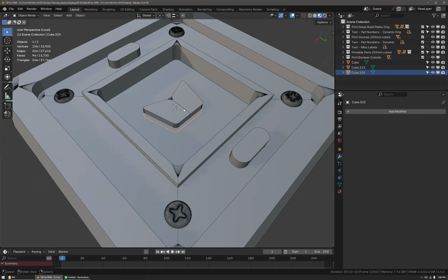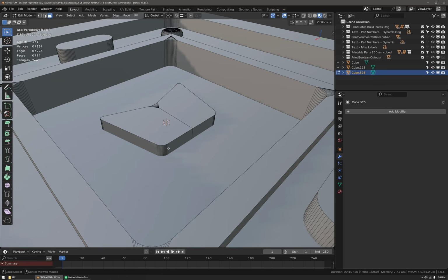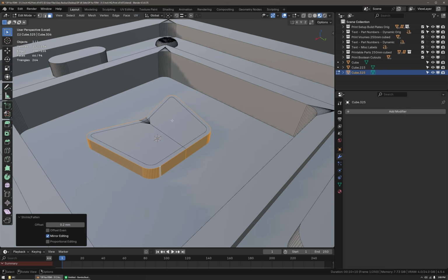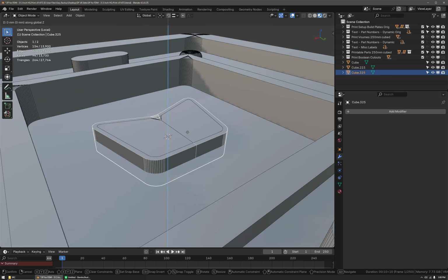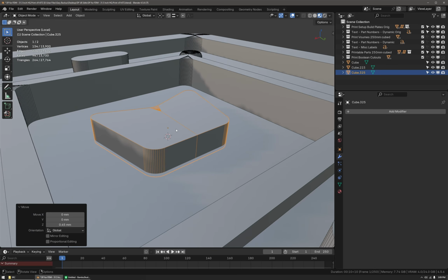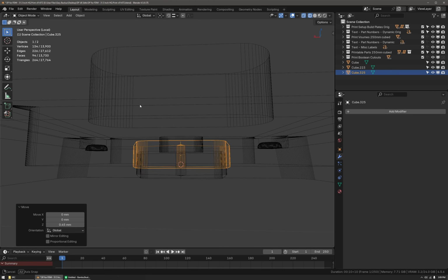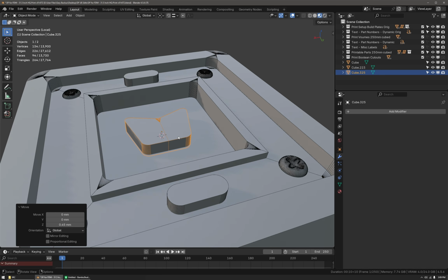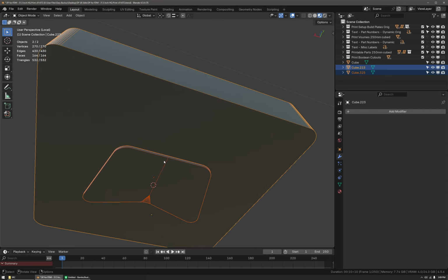So now you can see that we have two copies. This new copy, I'm going to go into edit mode with face selection, select this face loop, press Alt S 0.2 because I want to have 0.2 millimeter gap around here. And now I'm going to press G Z 0.45 to move it upward. So now if you can see, this is going to be a cutout for the next object. So let's press / to unisolate that object. Let's go into here. Now we've got this selection isolated.